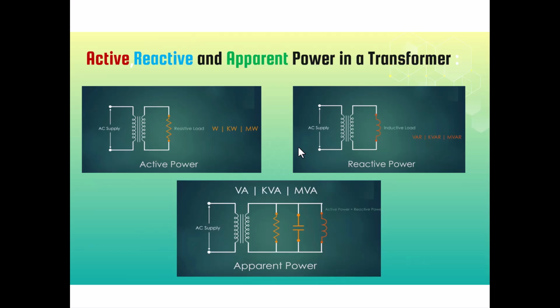It defines the total electrical load that the system must supply and that all equipment must be rated to handle. Together, these three components form the power triangle, a foundational model in power engineering. It not only quantifies the energy flow in a system, but also drives decisions in equipment sizing, power factor correction, grid stability, and energy efficiency. In summary, real power powers the world, reactive power makes AC operation possible, and apparent power determines the true burden of the infrastructure.